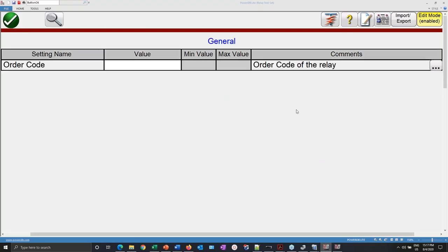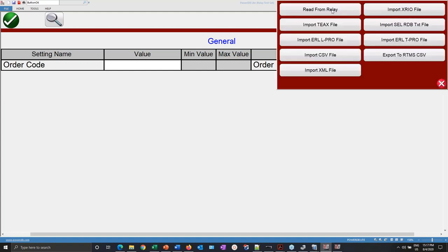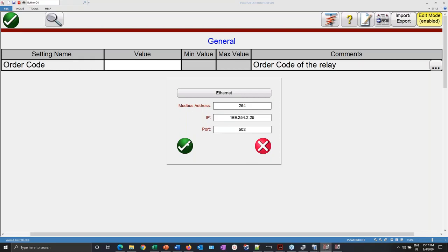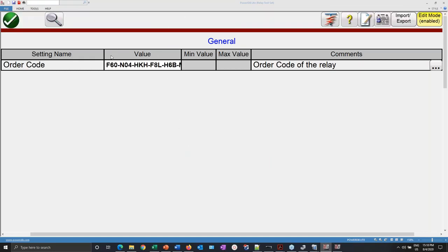So now I can use this to import that element into my test sheet. I can use that same procedure. If you see, it was very fast. I just read the order code of the relay into my test sheet. Remember, you don't have to read every single element of the map. All you need to read into your test modules are those elements that are relevant to the tests that you want to perform with that test module. So you don't have to go over the thousands of elements that you have in the map of the relay. But you can read a few of the, let's say, overcurrent, overvoltage, distance element, frequency, etc., and you can convert them into a usable format that you can then assign to the different tests that you have on the relay.